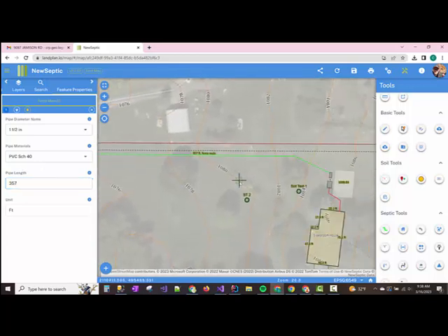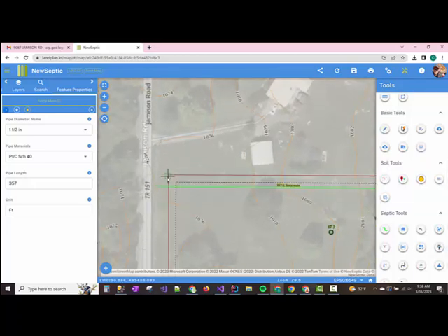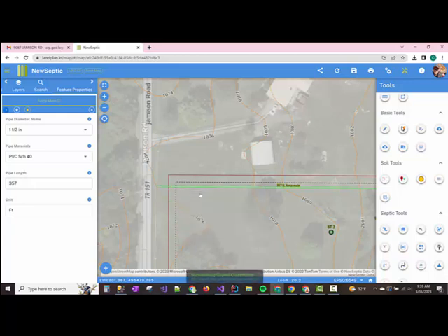So we have our force main there, and the only other thing we need to do with a discharging system is in Ohio, they require you to have the coordinates for the discharge point. So the lat long coordinates, and what we can do is hover our cursor over the discharge point, right click, and click copy coordinates.